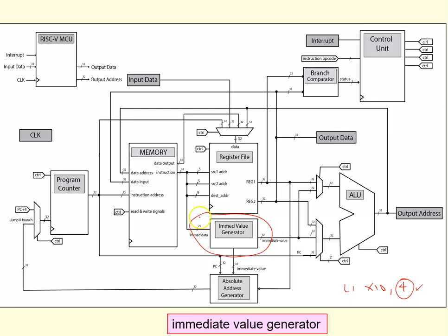But anyway, all this module does is take values that are not 32 bits and make them into 32 bits without changing the value of that number. It does so via sign extension and zero extension.